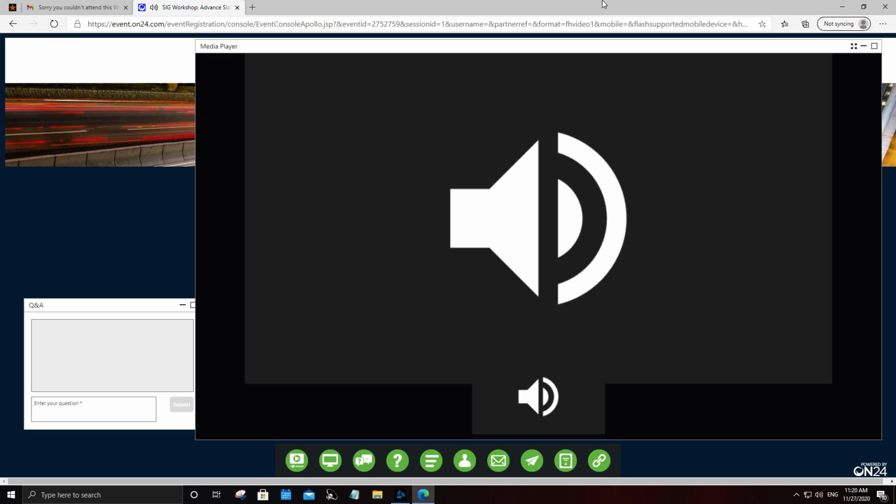Can we do soil structure interaction using RAM Concept? I would say that with the help of, again, the well-known integrator, the ISM, Integrated Structural Modeling, it is actually possible. But if you are looking for a post-tension mat slab or mat foundation to be integrated with a soil model, that would be difficult.